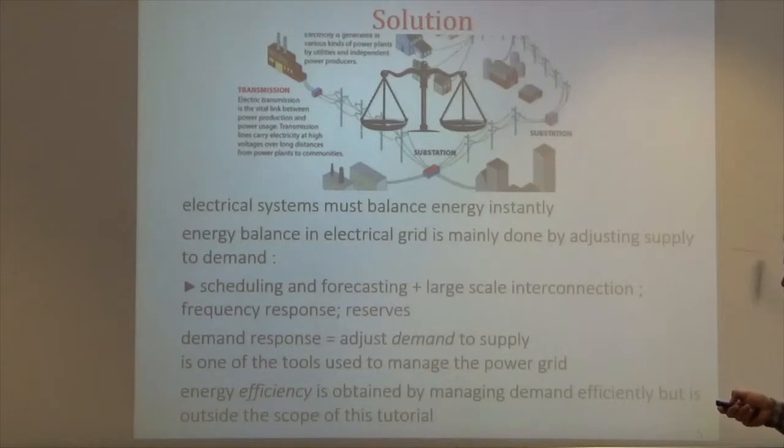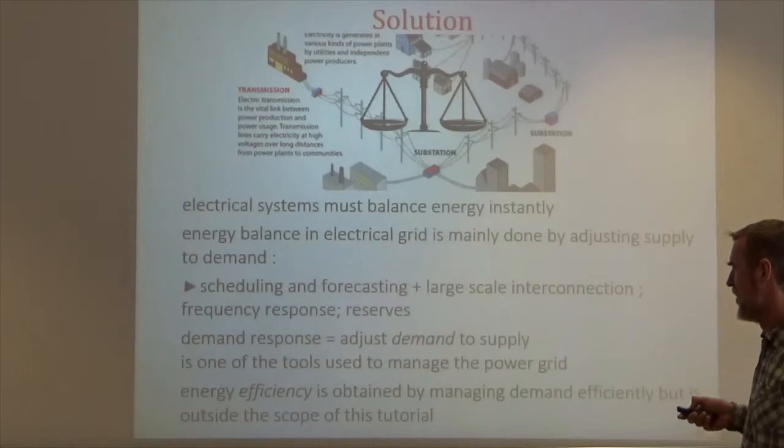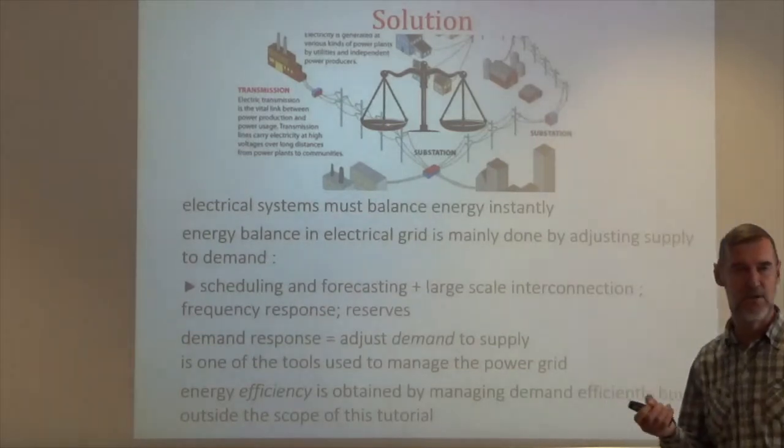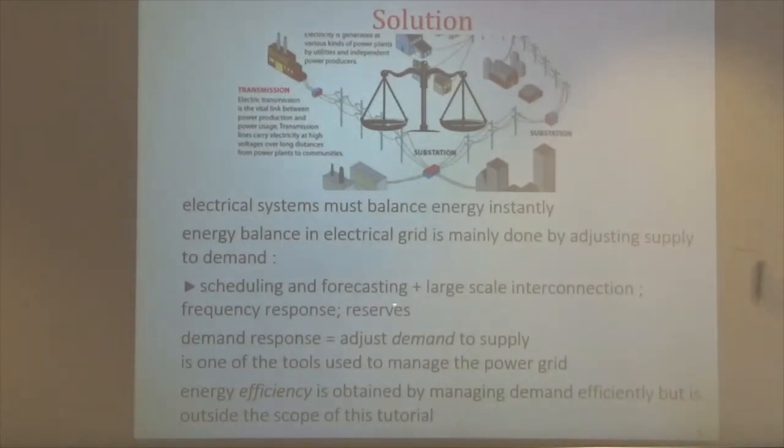Then you have secondary reserves that are signals that are sent to generators to adjust their production, increase or reduce their productions. And so it's called secondary response when it's done at the time scale of seconds. And when it's done at larger time scale, it's called tertiary reserve, where it's typically at the time scales of hour.